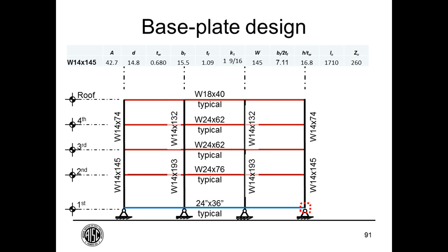I suppose, well, I haven't seen such a design. I suppose there are different methods where you could allow some rotation, but those would be unusual connections. As for fully rigid, that might be a little unconservative in terms of member selection to meet your drift limit.